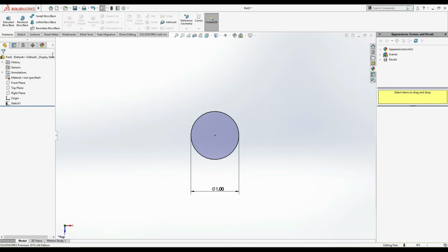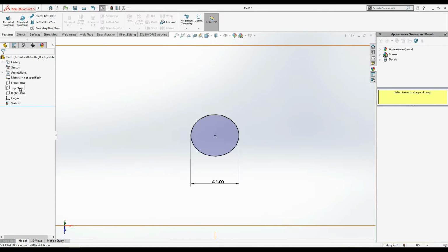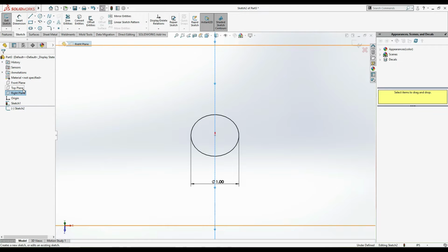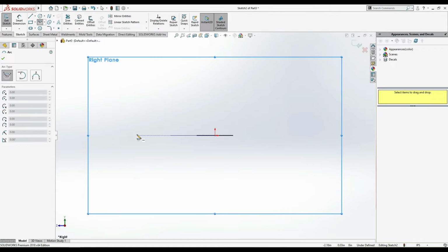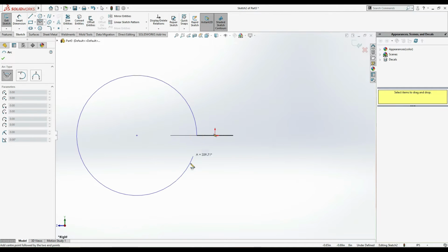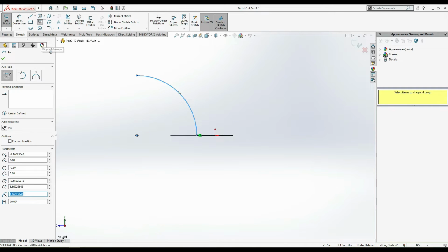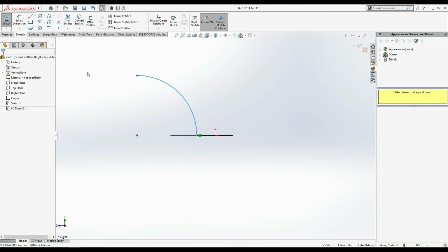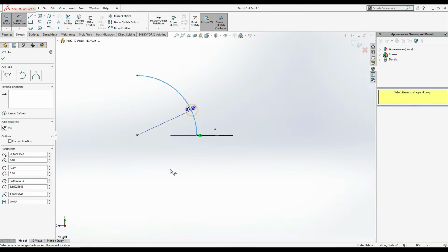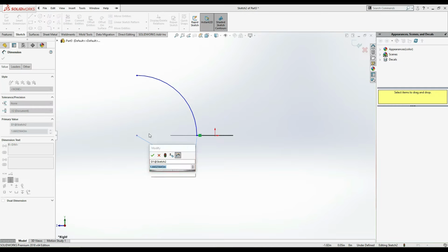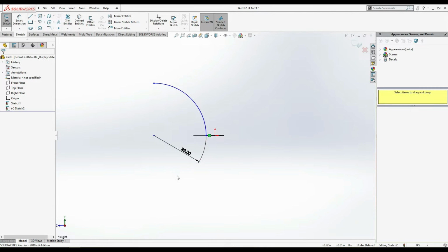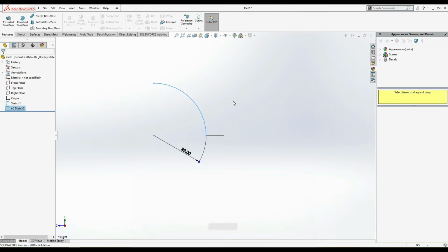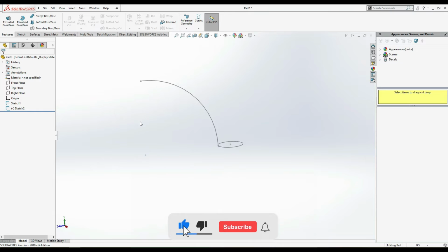So one is done. Now for the next, take a parallel plane: right click, sketch, Ctrl+8, and now I'm going to select this arc from here to here. I have made an arc. Next, escape, give it a dimension. I'm going to make it 3. Okay, it's going to be big, but let's see what happens. Now we have made one profile and one path.